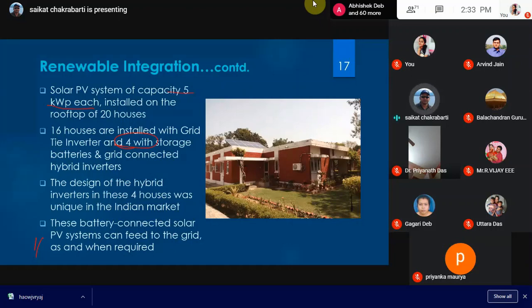And these installations need to be cleaned every, let's say, 2 weeks, because we have a very high level of pollution here. Dust particles, bird droppings, and they accumulate on those panels. Okay, so they need to be cleaned. And by the way, this is a very significant thing. We have observed that if a lot of dust accumulates on the panel, the efficiency goes down drastically, almost goes to half. So cleaning is a very important thing. If you have a solar panel on your rooftop, please make sure you are cleaning that.